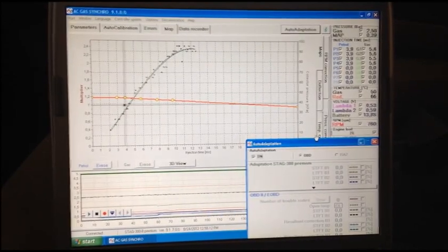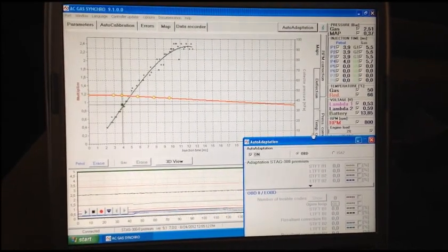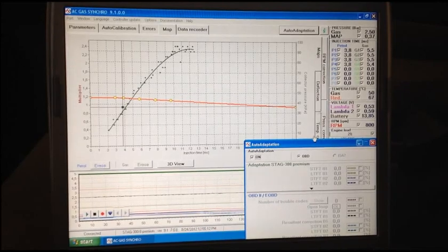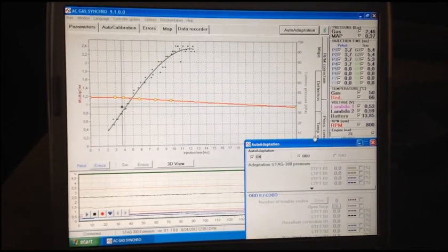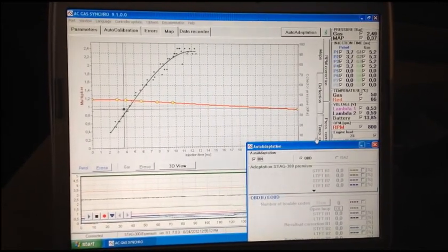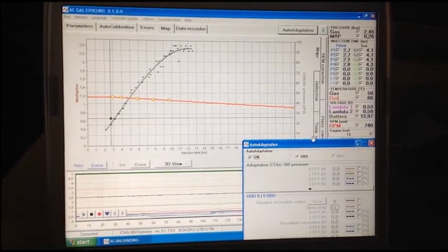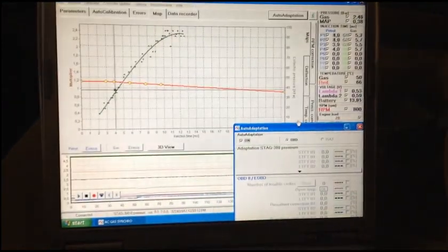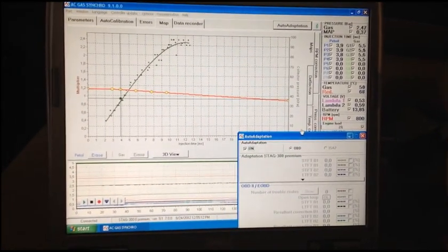It hasn't made many alterations yet, so feather the throttle a little bit, kind of gradually get into it, and it'll be making corrections while you're driving, and get better and better. Drive it for a good 15 minutes or so, and you'll start feeling a better and better response as you move along.